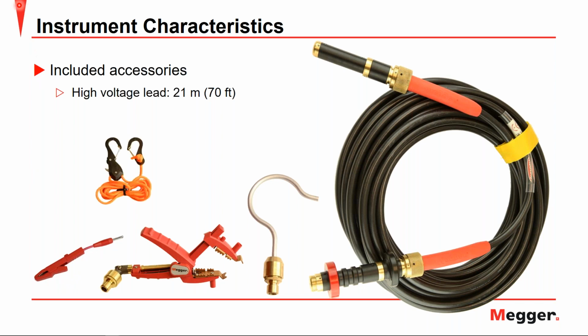And then you have this nylon string, which is more to support the high voltage lead. As we mentioned before, when performing a test, we don't want the high voltage lead to rest against the tank or the bushing. So this nylon rope here can actually be used to tether this high voltage cable up and out of the way of the transformer to keep good clearances.